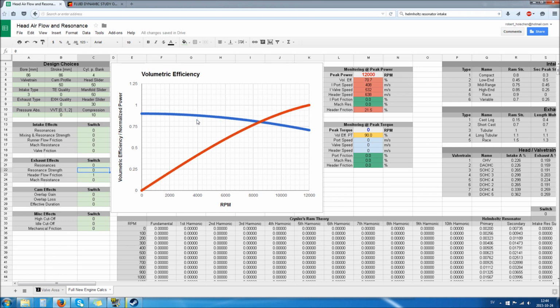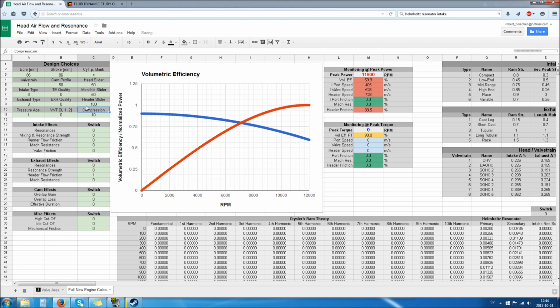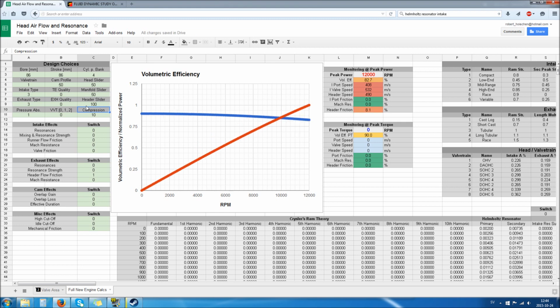is just an effect of how quickly your exhaust gases are flowing through those primary pipes. And the longer they are, the more friction you get. And this is now a pretty long pipe. Let's make it even longer. And you see more friction, and if you make it shorter and more flowy, more diameter, then you will remove the friction to a large extent and have more free flow. But on the other hand, you will shift up the exhaust resonances, the rev range, quite a bit, which is maybe not a desired feature, and you want to compromise on that.